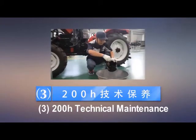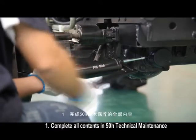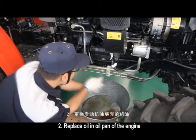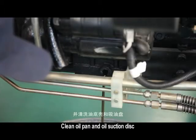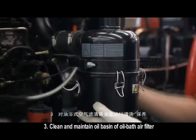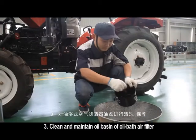3. 200-hour technical maintenance. 1. Complete all contents in 50-hour technical maintenance. 2. Replace engine oil in the oil pan of the engine. Clean the oil pan and oil suction disc. Clean the oil filter. 3. Clean and maintain the oil basin of the oil bath air filter.